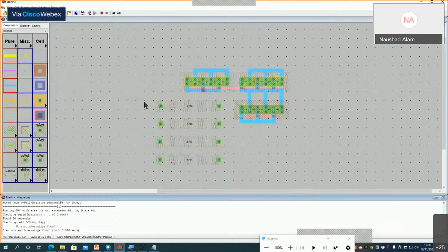That is why we have been taught in analog design principles that we shall avoid the use of passive components, because large value passive components consume large area on an IC. So I hope I have made this point clear.